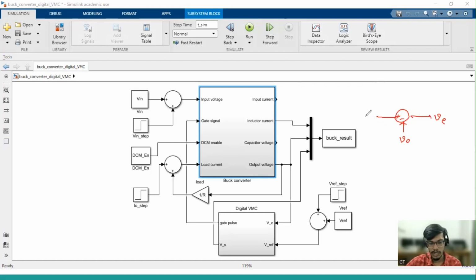If you put a DAC here, and you give V reference in digital, now you can program the V reference. So the output will be analog. If you do this, they call it housekeeping, because the entire circuitry is in analog and only a small part is in digital. So this is called the housekeeping thing.